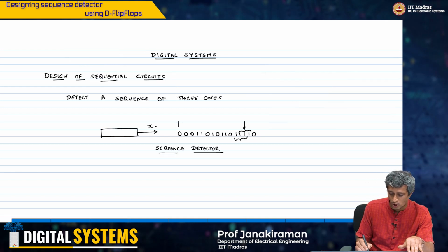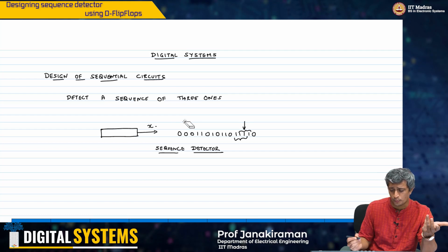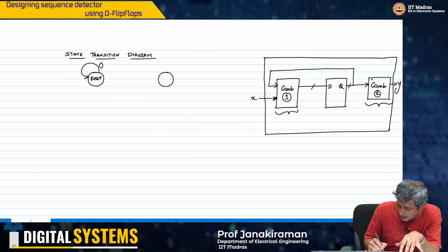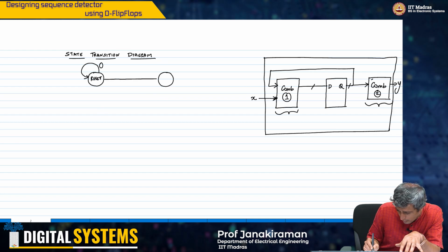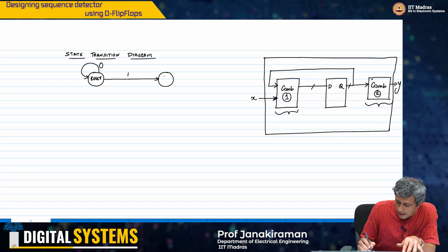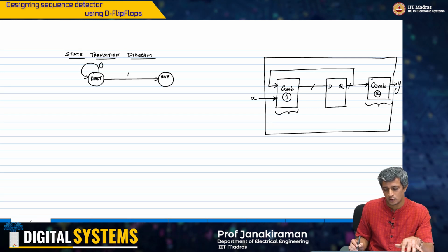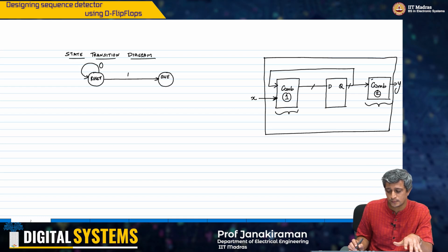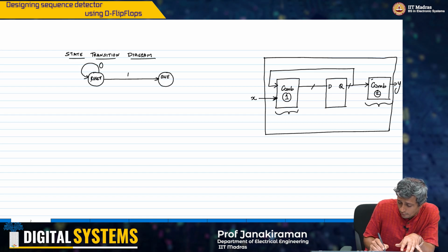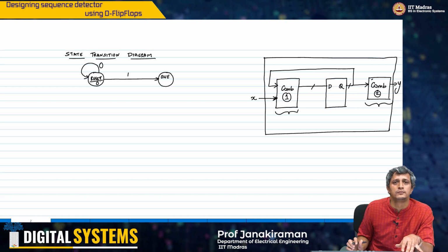It's like, you got a 0, so there's no 1, so you cannot proceed to the next state at all, right? Now, on the other hand, if you do see a 1, I'll go this way, okay? The input is a 1, then I go to, I'll call it state 1, okay? That means I've seen 1, 1, that's what it means. And then I'm going to say that, of course, the output from this should be a 0, okay?